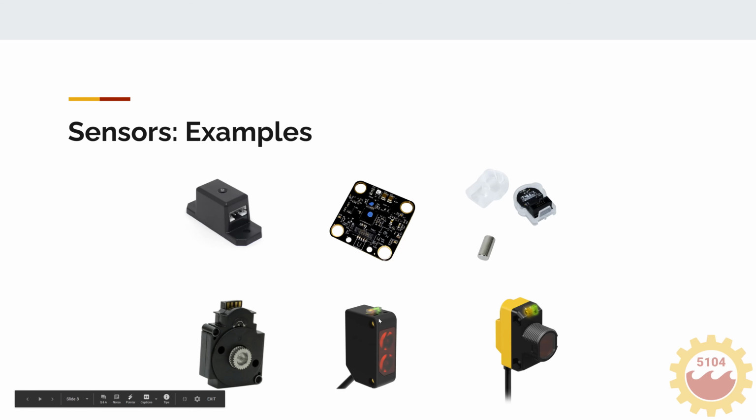These are some sensors that are super useful. These are both photoelectric sensors, and basically they're kind of like the Hall sensor, but they're all light based. And again, they have this LED on top. They also have one for power and one for if the signal's true or false. The reason they're super nice is they're really easy to mount, and they are a little bit expensive, but they last forever and they're super reliable.